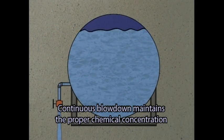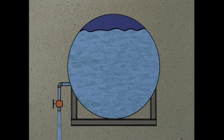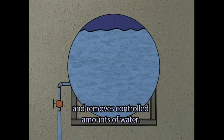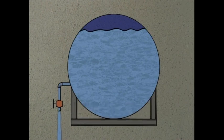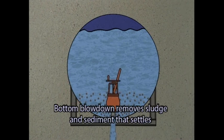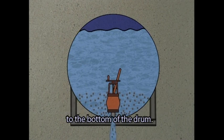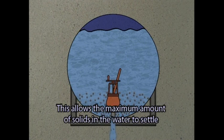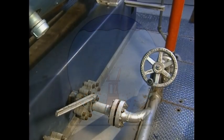Continuous blowdown maintains the proper chemical concentration in the boiler water. Continuous blowdown is performed automatically and removes controlled amounts of water. Bottom blowdown removes sludge and sediment that settles to the bottom of the drum. Bottom blowdown is best performed during light loads. This allows the maximum amount of solids in the water to settle to the bottom of the boiler drum.